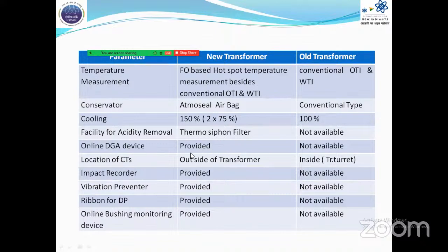The concentrations of the key gases of DGA, like ethane, methane, ethylene, acetylene, nitrogen, oxygen, hydrogen, carbon dioxide, and carbon monoxide, are detected from those dissolved in oil by the gas chromatographic method. The entire arrangement is provided in the device itself, which is connected to the transformer, and the process takes place in the transformer in service.